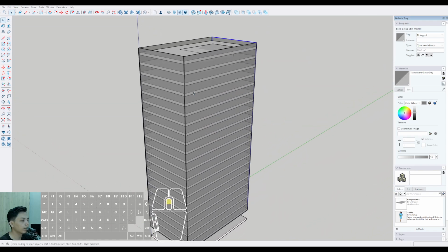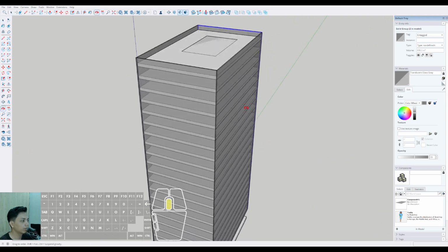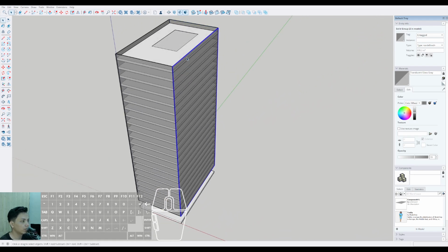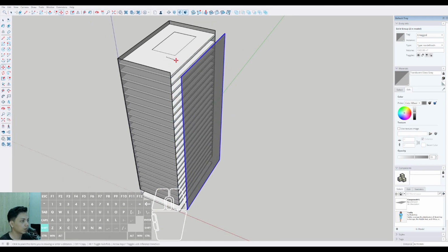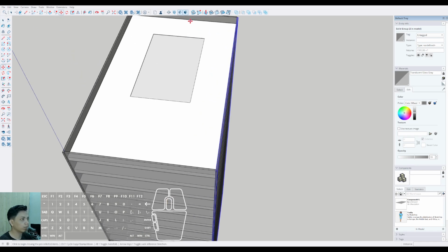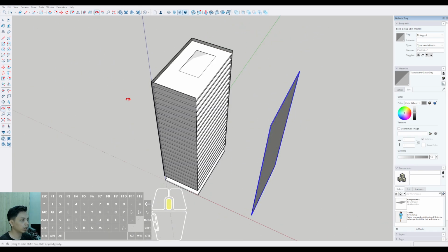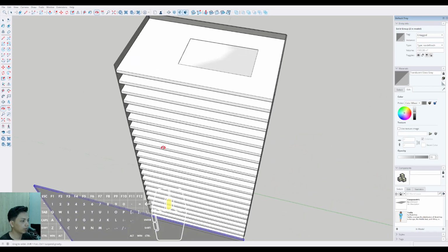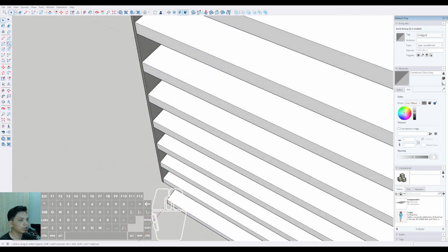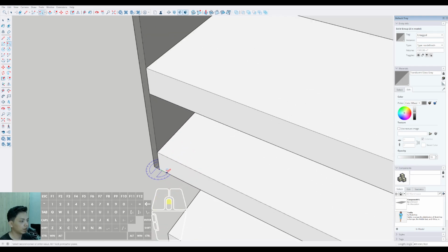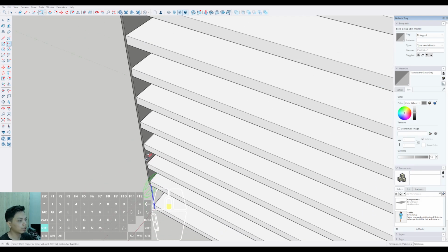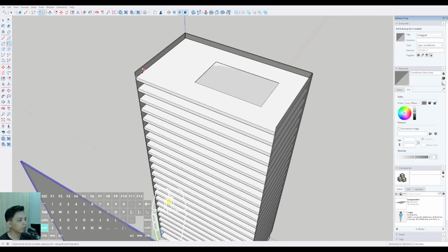Okay, so I will give you an example for making the frame of the outside. We can move it first to another place. Okay, we can move it to another place, for example, just like this, and then we can set the frame over there using the frame material. We can use the rectangle, click start from here, and then we can type maybe around 150 millimeters for the width of the frame, and then we can set the height of the frame up to the rooftop over there.